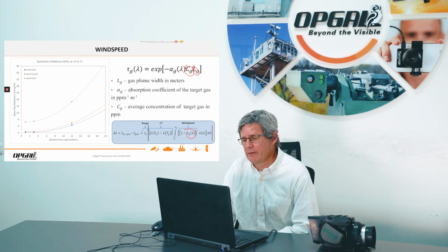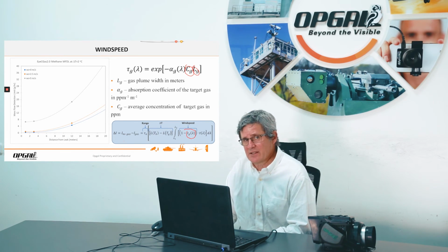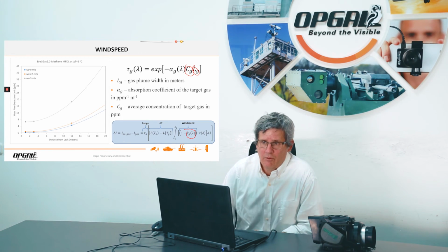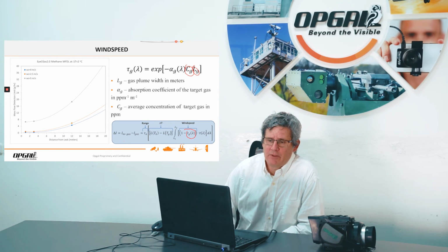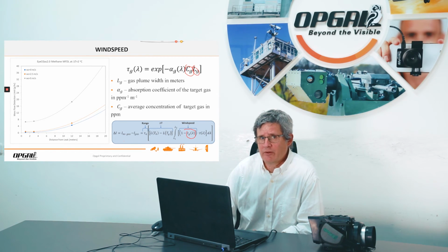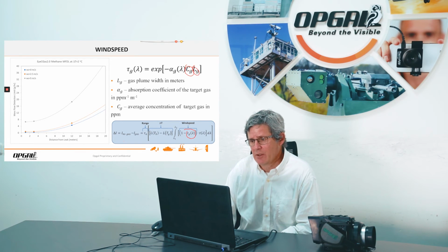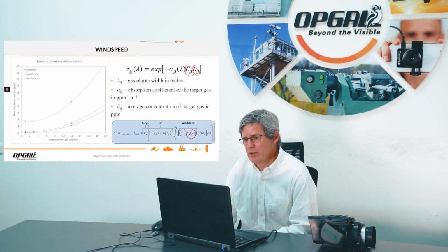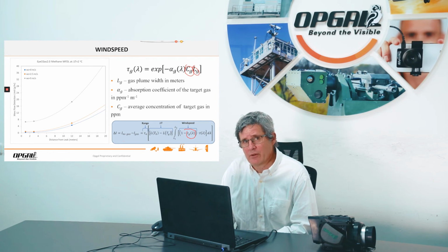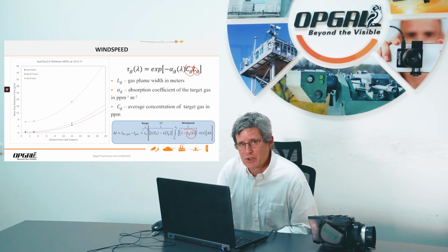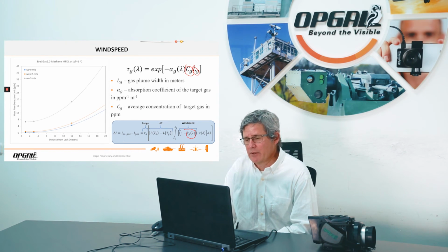The other thing that I would like to mention is we define sensitivity as mass flow detection limit, because this is the way that we can do control release in a known leak rate and see at what temperature difference and at what distance we can see several of these gases. And then we can use theoretical information on absorption coefficient on any gas and extrapolate this, knowing also the transmission of the bandpass filter of the camera.